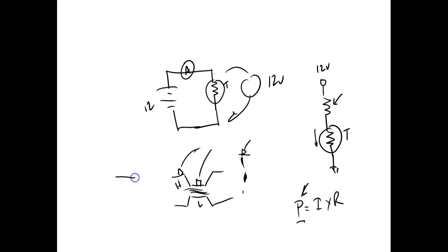They got one called a vane too, where they actually put a little vane in here. And then it's got a calibrated spring on it. And then when the flow moves against it, it does what? It pushes that little vane out of the way. How far it pushes depends on the tension on the spring. And they can measure that deflection. They usually hook a potentiometer up to that thing, which is pretty neat. But I have never seen them use a thermistor to measure the flow.